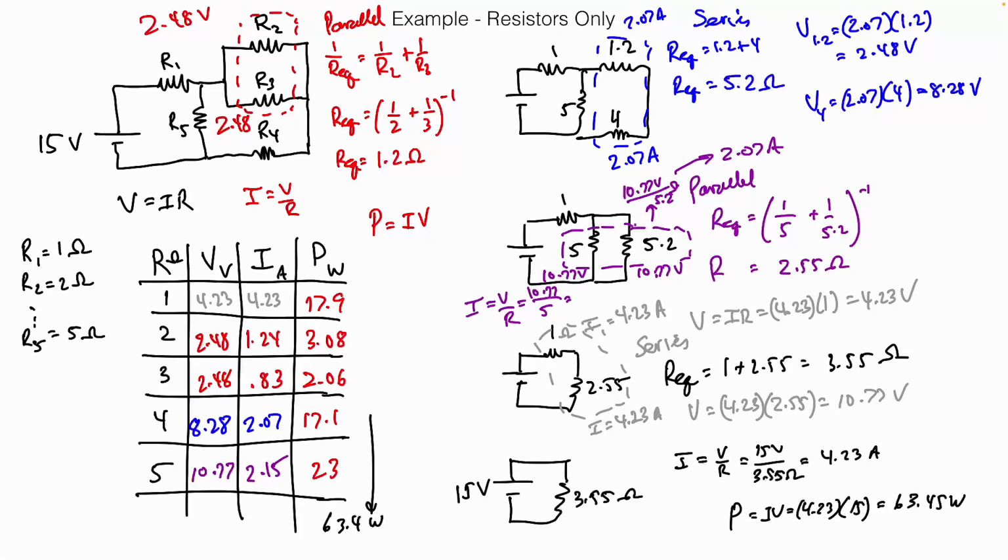And so that's a check that can be performed if your circuit consists of nothing but resistors. If the battery is putting out current and voltage, whatever that power is, that is what the circuit uses up, regardless of its series and parallel connections. So that's typically something I'll do even if I'm not asked to do it. I'll check to make sure my powers add up.